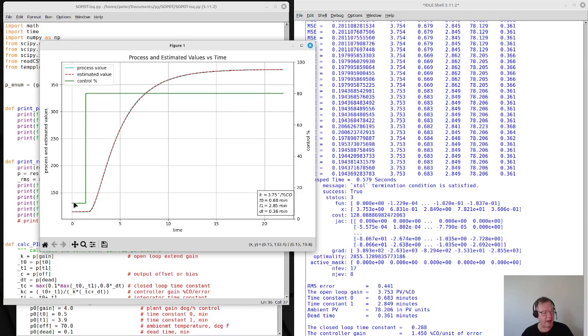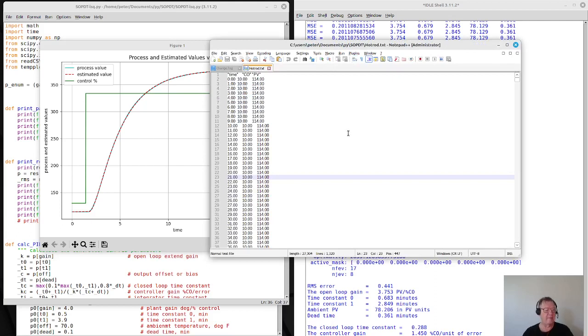what I got was a file in 2005 where there's a control output and there was the process value or the temperature, which is the cyan line. And the goal is to compute the parameters that will give a differential equation that will simulate the actual response. And what I was provided with is a comma separated or space separated variable file where there was a time in seconds, the control output in percent, and the process value in degrees. And I think this is Fahrenheit.